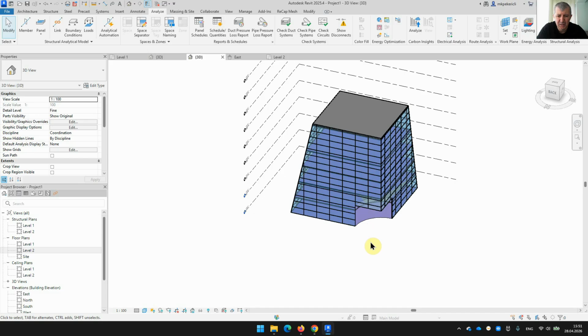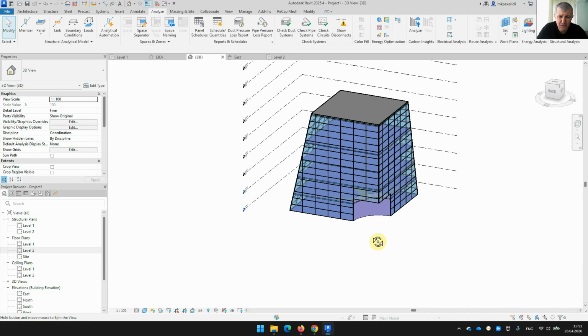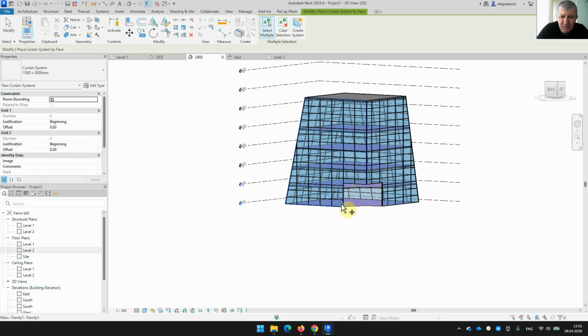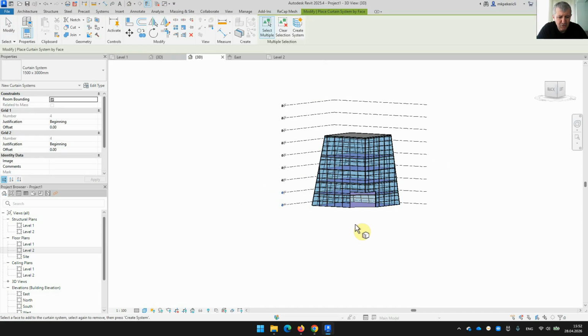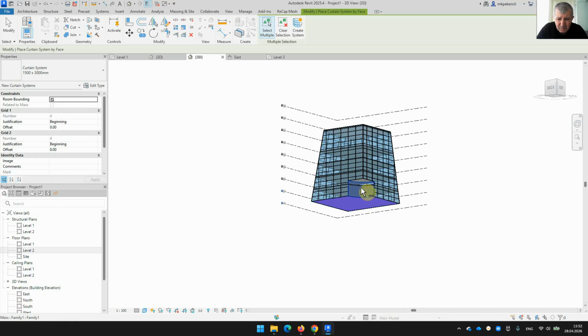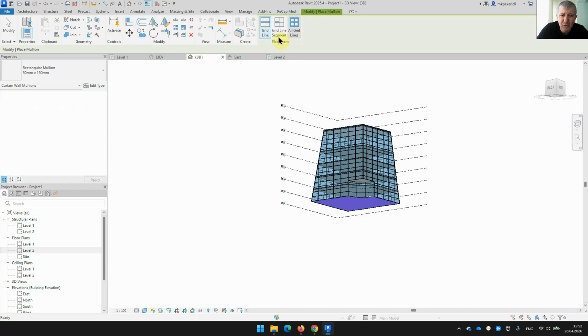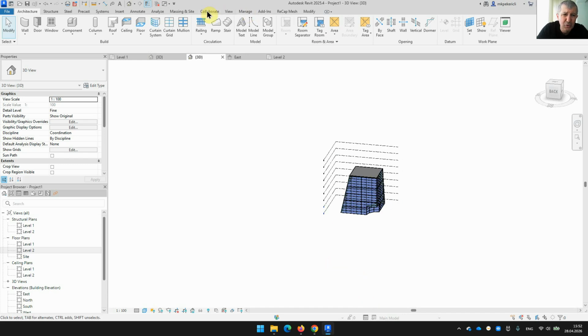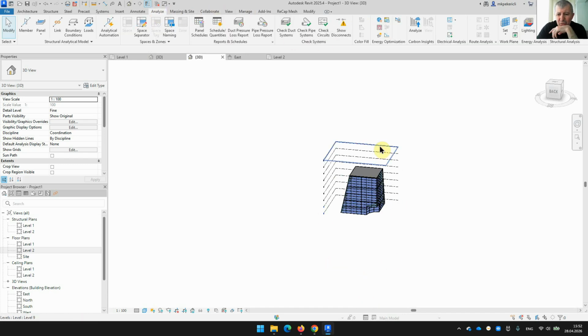Meanwhile, I think I didn't put a wall onto this surface. So go to basic insight, curtain system. Can I choose that one? It's a bit tricky. Yeah, this one. Create system. Okay, perfect. And then architecture, all grid lines. This one. Okay, now it's a closed building. Now we go to analyze. Okay, now we have created our building.